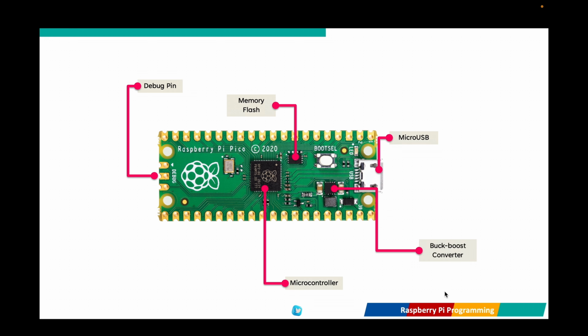The Raspberry Pi Pico is designed for low power applications, consuming only a few milliwatts when idle. This makes it ideal for battery-powered projects like the ones used in remote areas, remote sensors and wearables. The 3.3V fixed output buck-boost SMPS converter regulates the power supply.